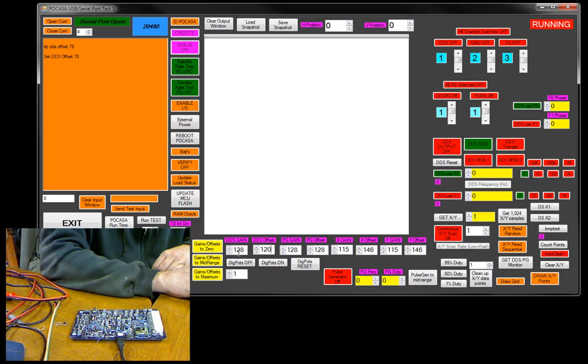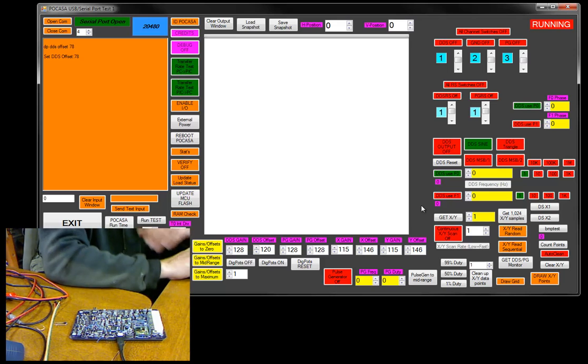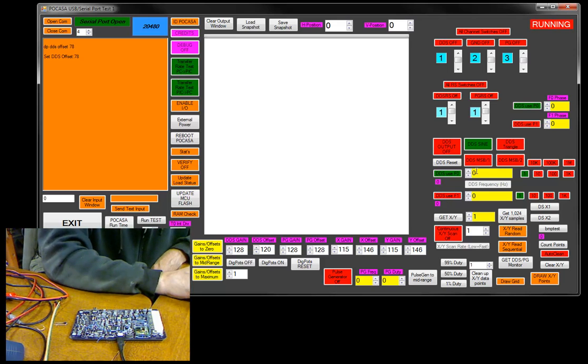This is to set the voltage coming out of the DDS. This is to set the offset, whether it's centered on 0, a little above, a little below, all the way above the 0 line, all the way below. This is a 4-quadrant DDS generator. Does positive, negative, both ways. Let's make a frequency here, 60 hertz.